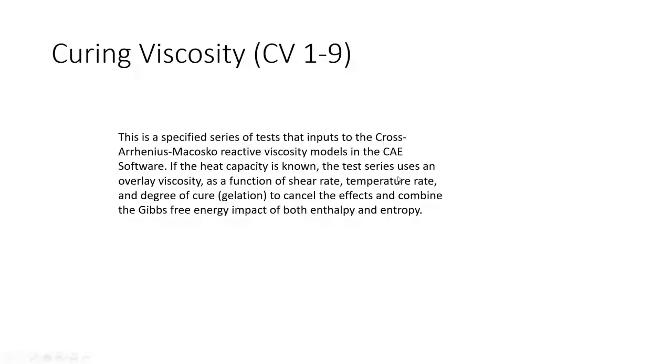When we start talking about high pressures, high flow rates, and fast fill rates, we really have to understand the Gibbs free energy impact of both enthalpy, the heat aspect of curing, and entropy, that of mixing. So when things are under high shear, they cure faster. That's why LSRs cure so quickly and why injection machines are so efficient.